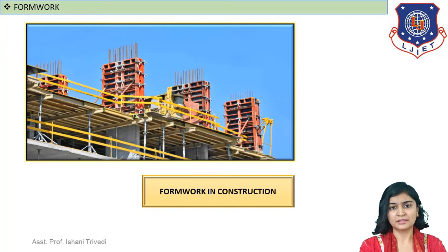I had discussed that various precautions have to be taken when you are placing your concrete mix. I also discussed that you have to place the concrete layer by layer and simultaneous compaction has to be done. So now the point is, where are you going to pour this fresh concrete mix?